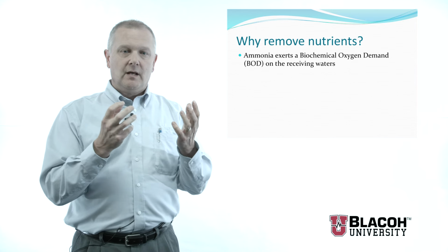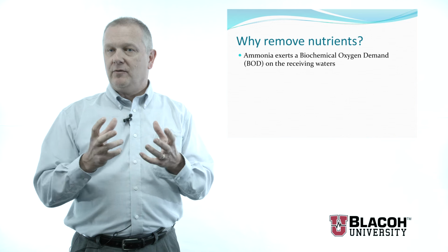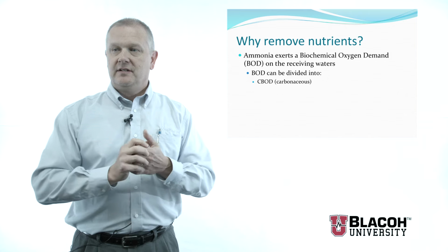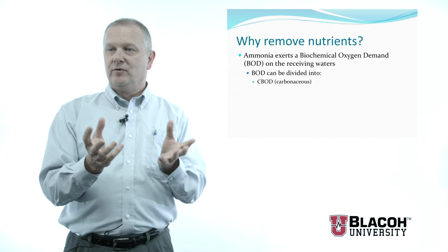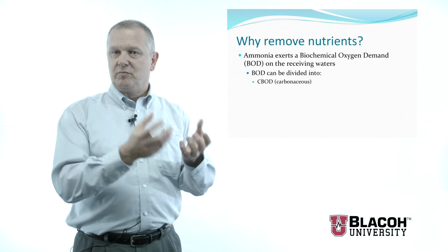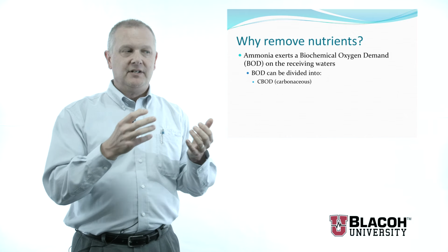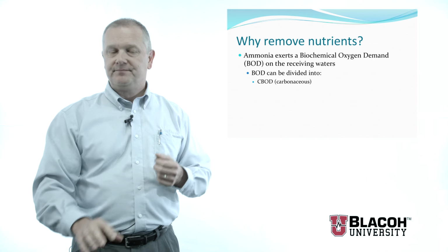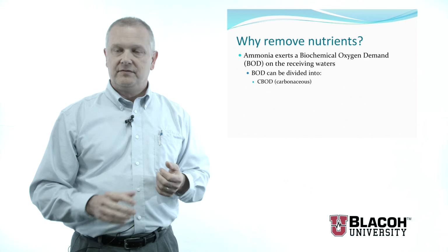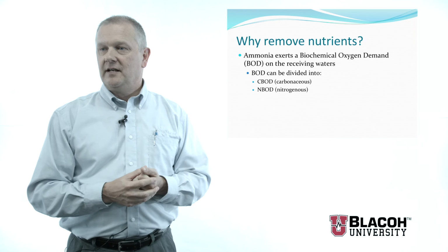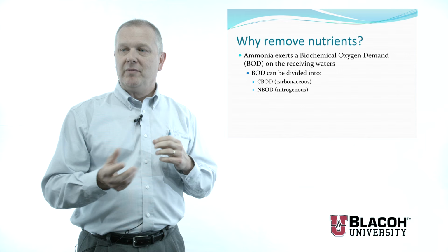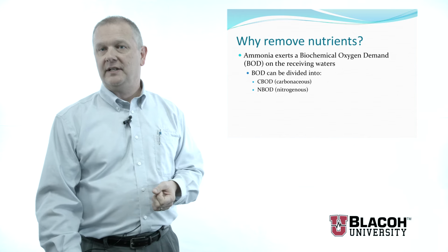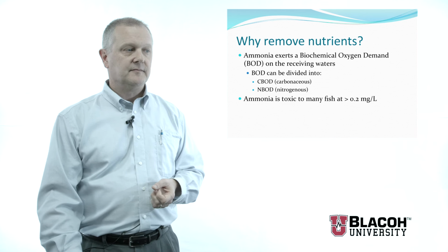And usually when we measure BOD, we're talking about carbonaceous BOD, which is the 5-day BOD test that we normally run, where the microorganisms break down the organic material into carbon dioxide and ammonia. But the ammonia itself has an oxygen demand as well, because it can be biologically broken down, and that consumes oxygen from the wastewater also, and in some areas that's a problem.